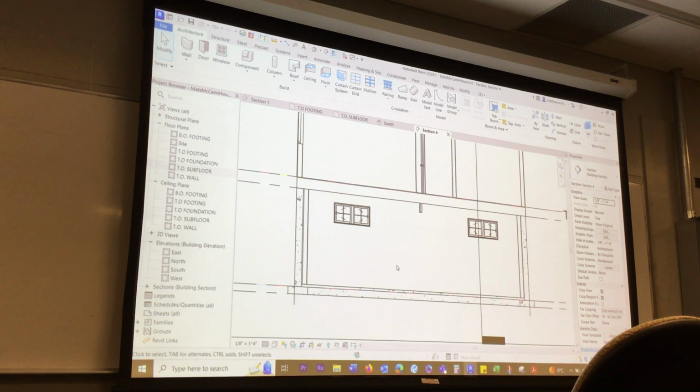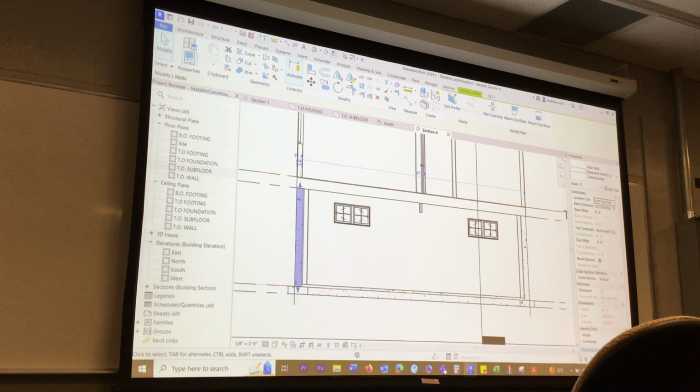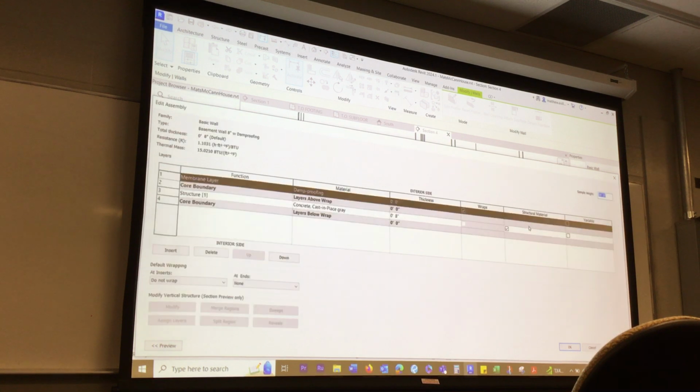Okay, so let me think, what's another big thing? Oh, it's putting the basement under. Most of you were able to do that, so that's pretty good. That's copy aligned to selected levels, but it doesn't do you any good when, core face, that's the other problem too. A lot of you, things like basements and stuff, you moved them under, but you're drawing the center line and stuff like that, and then not checking it, right? Like, I had a few where the basements were lined up 8 inches in, because you're drawing to the wrong thing. Before you start drawing, you have to check your location line. So core face on this is just the outside of it, because you remember, everything when we build it has a core face.